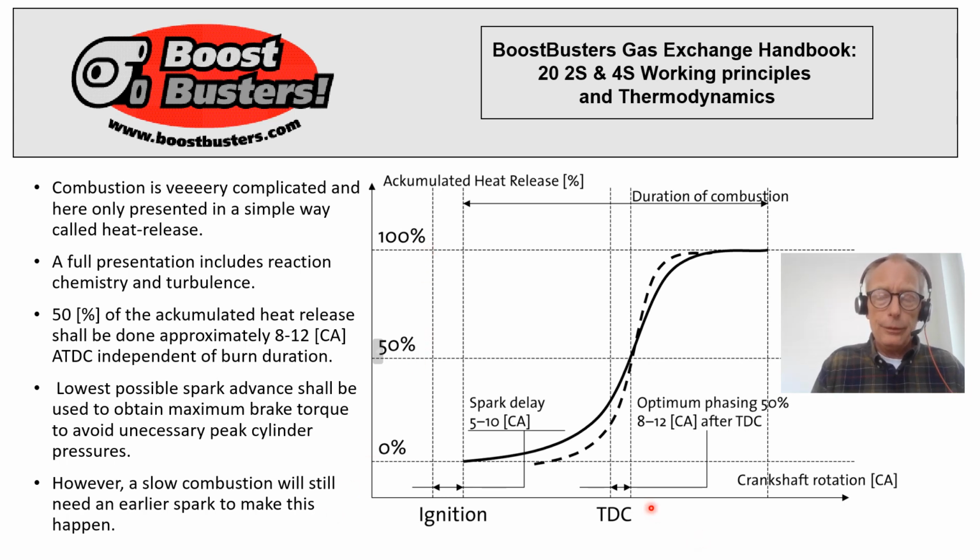We have the top dead center here. The combustion always takes place as an S-curve, S-function like this. It could be a quick burning system like the dotted line here, or a more slowly burning system. That depends on the geometries of the engine and several other things.